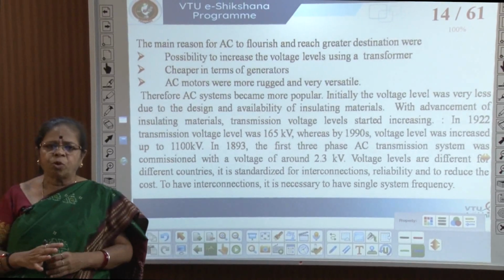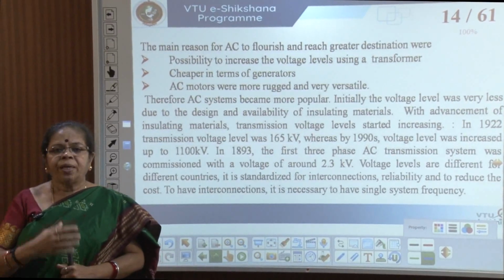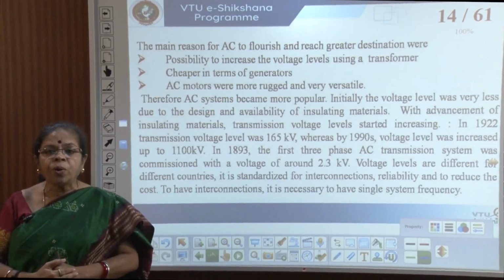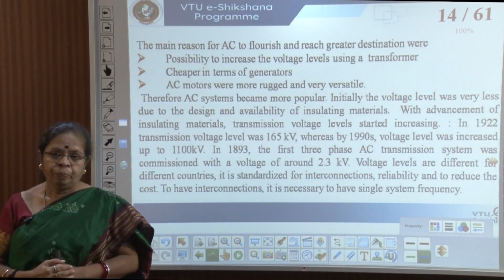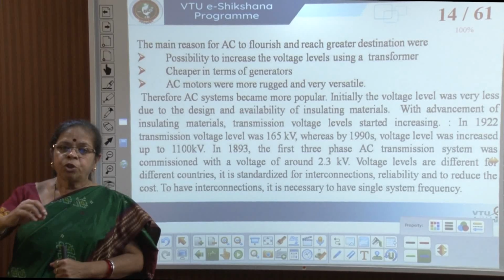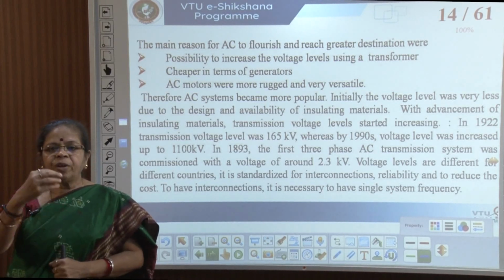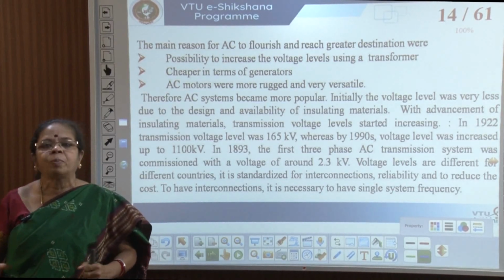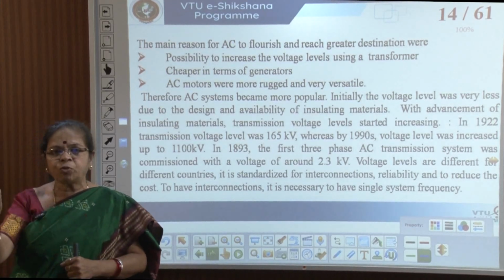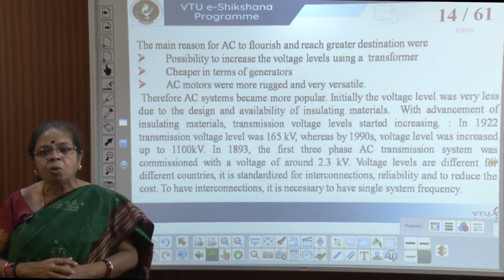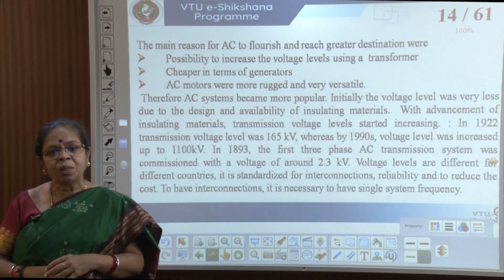Now, when you think of a transformer, you would have studied in transformers, there is a lot of design involved, right? So, I need to design the coils, I need to design the core, we need to design the insulators, the cooling systems and so on. Well, I have a strategy to transform from one voltage level to another level. This is theoretical. So, V1 by V2 equal to N1 by N2 is a mathematical formula, but I can't just have any voltage I want. I can't transform, say for example, 10 volts to 10,000 kilovolts. I can't do it. Why? There are so many limitations, right? As I told you, the design of the transformer comes into picture.